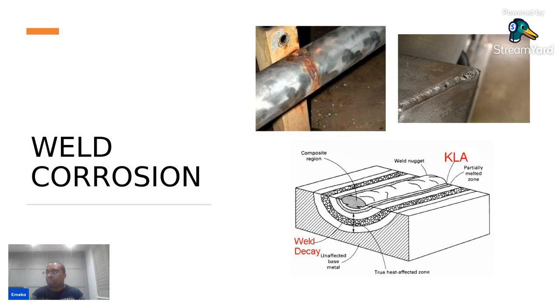From the first picture, you could see that the parent material is intact because that's the cathode, while the welded zone is showing signs of rusting, which is basically the anode. The welded section has become the anode, and that's the part that is becoming corroded. Another thing that could lead to weld corrosion is poor weld quality containing porous holes. Again, from the pictures, you can see that somebody has done a really bad job in welding there, and there are porous holes in it. And poor weld dimensions, such as weld roots protruding out, result in local turbulence flow and erosion corrosion at the weld area.